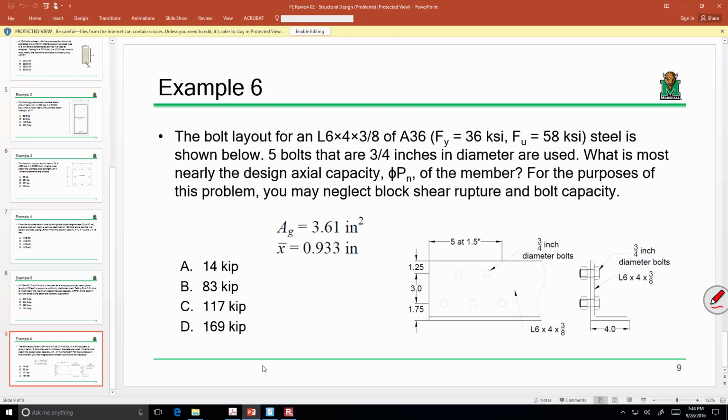All right. Now, this might be a little tough to see on the screen. I don't know how well it showed up on your handout. It's pretty reasonable. So we've got a bolt here, bolt here, bolt here, bolt here, bolt here. We've got 3/4 inch diameter bolts. They're staggered. Why would you ever stagger a connection? It ultimately has the opportunity to increase your cross-sectional area.